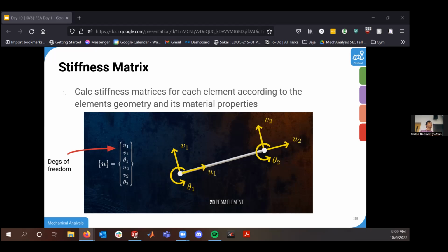For more complex geometry, your number of degrees of freedom also starts to go up. An advantage of solid geometry is that you don't actually calculate rotation for each one of them. You have just 3 degrees of freedom of translation, and rotation is accounted for in how it's moving in XYZ space. So this is like that first element, where it's not rotating in and out.